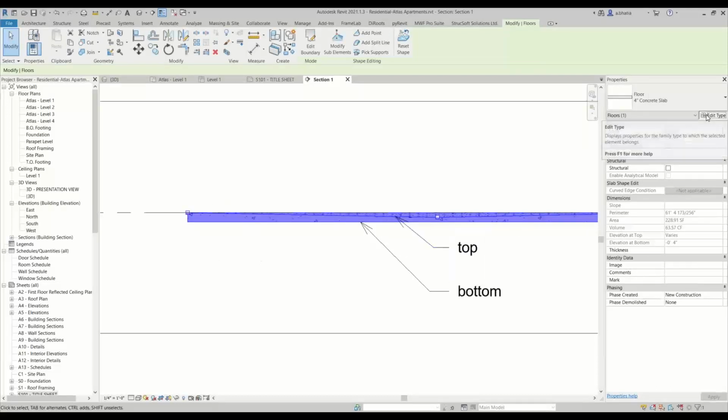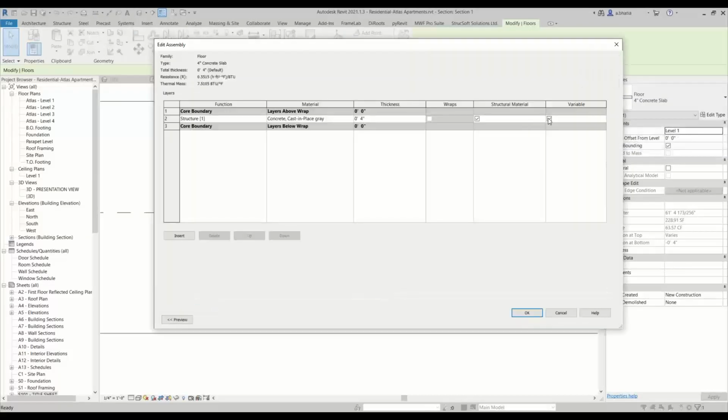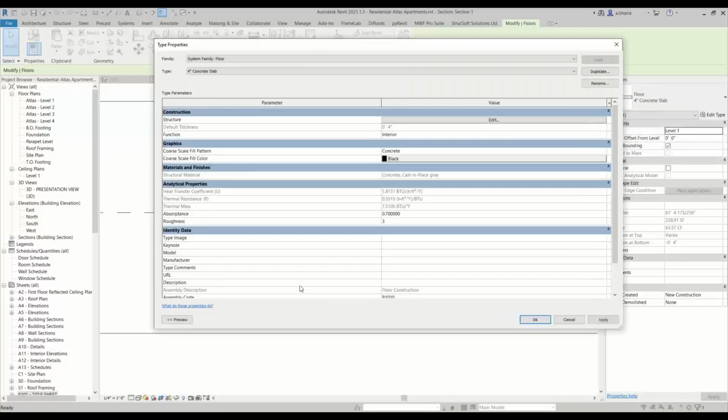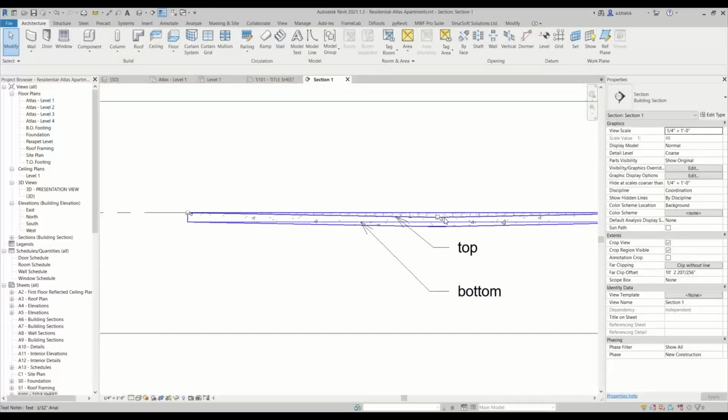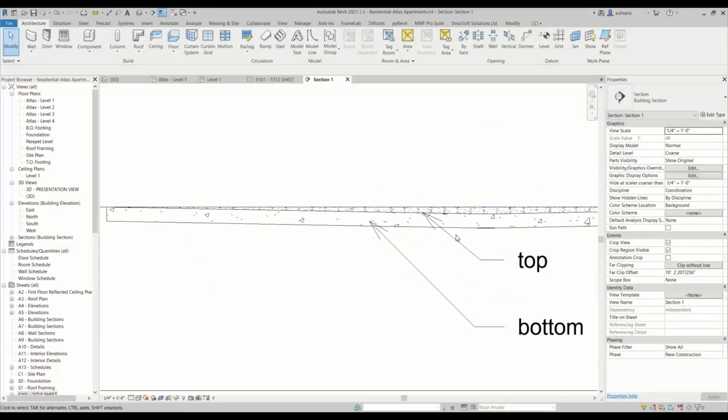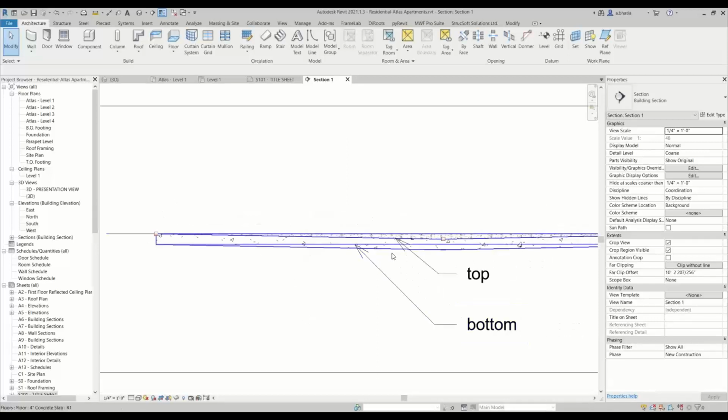If you did want to slope the top, however, you can do it another way. You could uncheck variable, we'll have it, and you'll still have your slope. And this is a much better and more acceptable way of doing things. You can definitely have that slope down here. Another thing to keep in mind is typically you would only have 2 slopes maximum in your floor, your roof,